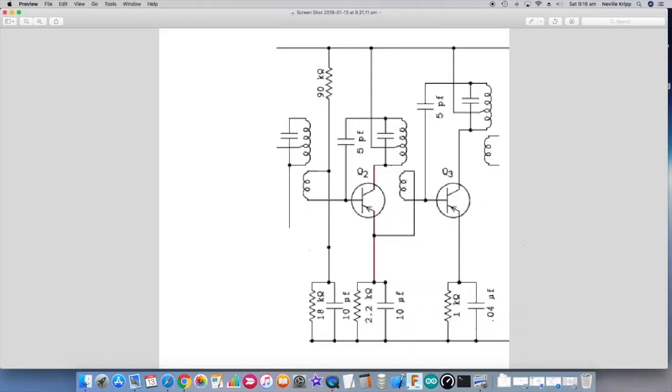version. Now let's take a look at a transistor version of an IF amplifier. So again, on the left side, this coil and associated capacitor is forming that first IF filter, if you like, on the output of the mixer, and it's also part of a transformer.